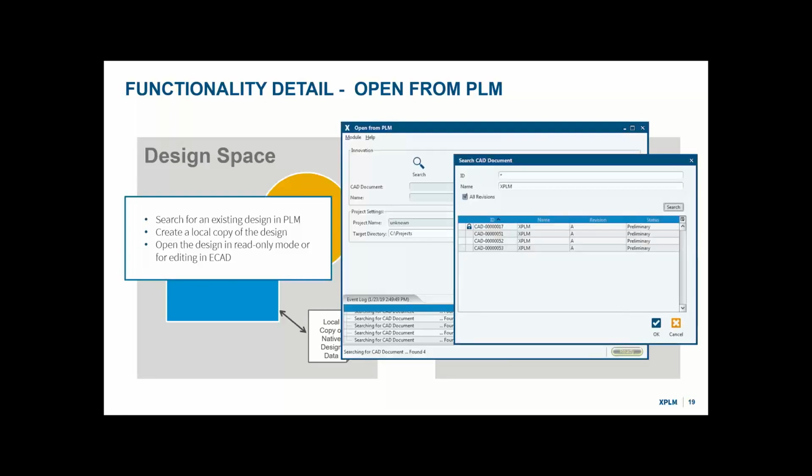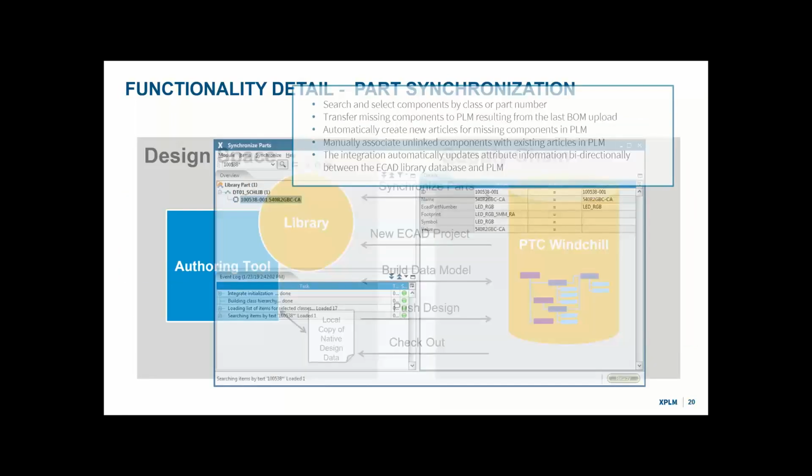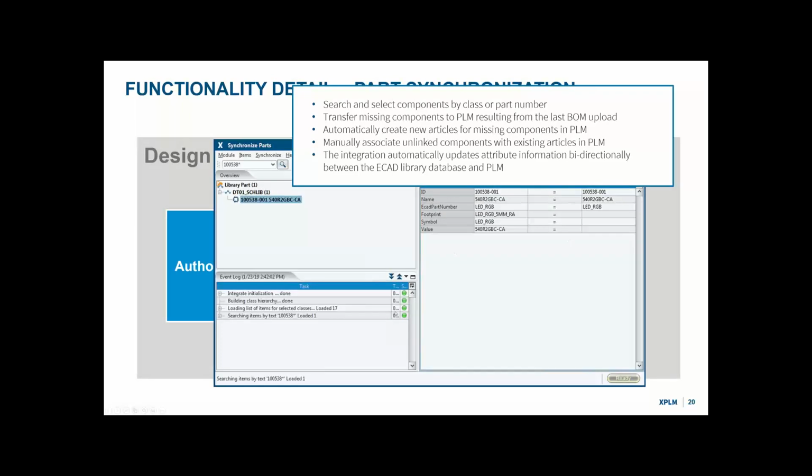Okay. So I was down here on the library, right? We were explaining there are three sections to our library interface. If you are running it manually, unless you're a really small customer, most customers automate this. You can just type in a part number you want to bring in. You can bring up another dialog that shows all the classes in your library. You can bring in an entire class at once, like all your resistors or ICs.